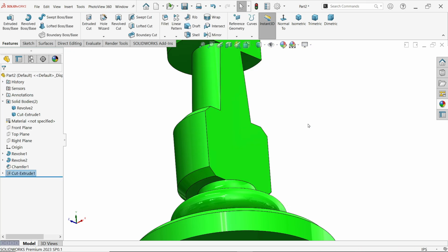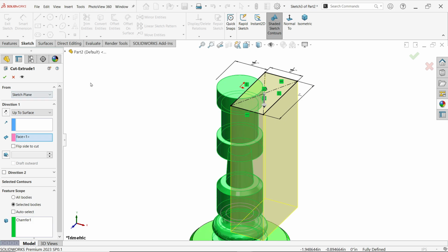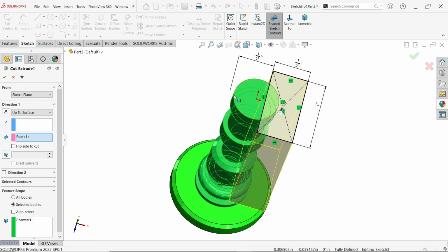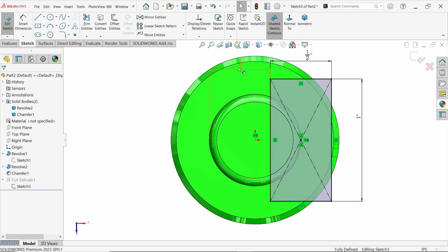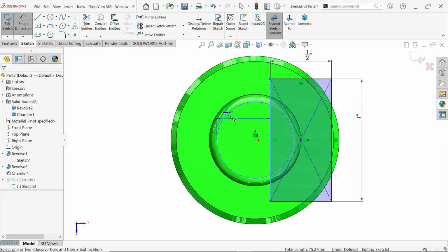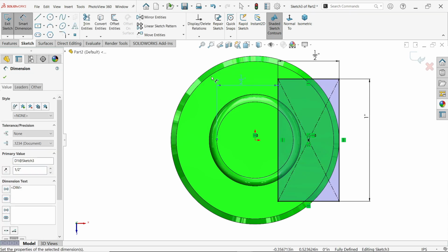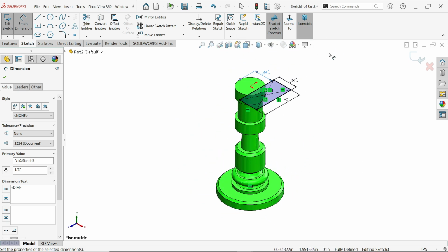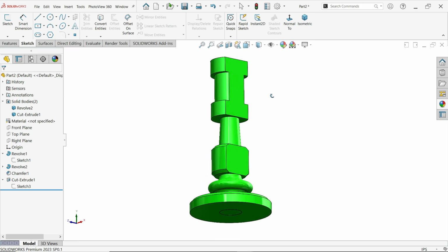Okay. Look. Now here we miss dimension. It should be from here 1 point, not from this outer face. So simply exit sketch, and delete this dimension. From this, hold shift key, then make dimension from here, and this is going to be 1.2 inch. Okay. Say okay. See.